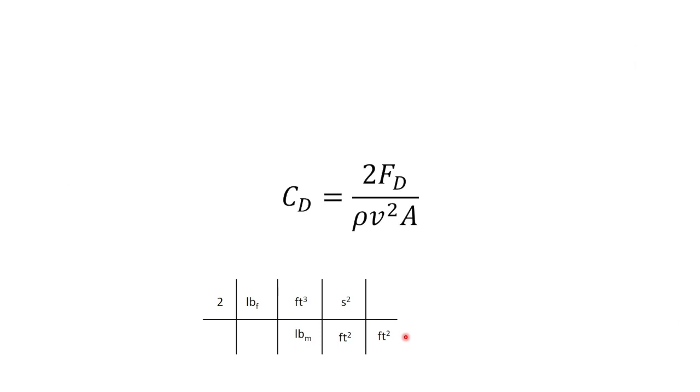Right now that doesn't look too unitless. Not much cancels out, just a couple of feet, and I'm still left with an extra foot, and the pound mass, the pound force, and the seconds. So if I go ahead and add in the conversions, and these are the two that everybody loves, they've got slugs involved. So I know 1 pound force is equal to a slug foot per second squared, because it's slugs in mass times the acceleration due to gravity gives me slug feet per second squared, which we call a pound force.